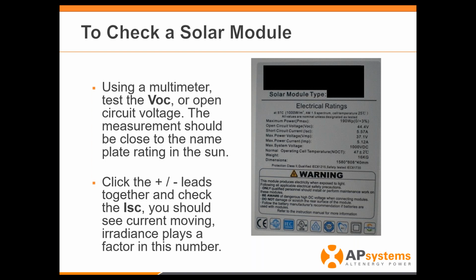If the voltage is supposed to be, let's say 36 volts VOC, and you're getting 24 volts, you have one of the strings on that module that is out. And that's exactly what he saw. He was actually able to verify with a multimeter that his module was bad.